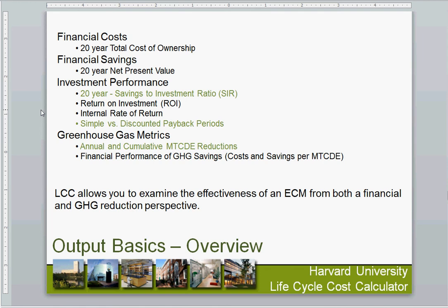An example of that would be if we're doing a major overhaul of a building that might be uninsulated. It's actually kind of hard. Retrofitting anything is very expensive. If we were just building a new building, the cost of insulation is relatively cheap, but to pull away interior finishes back to the studs or back to the wall, then come back and insulate, and then have to completely recreate that wall again is a very expensive endeavor.